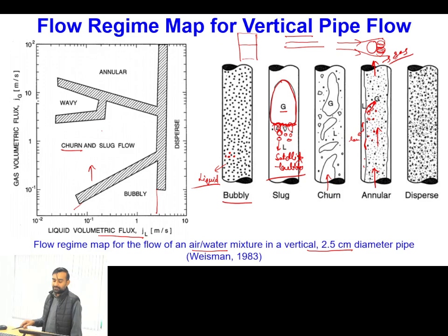Okay, so whenever we talk about heat transfer, particularly in boilers etc., whenever in the boiler tube near the end portion we have a significant amount of vapor fraction present in the tube, then we typically observe this type of annular flow. Okay, and